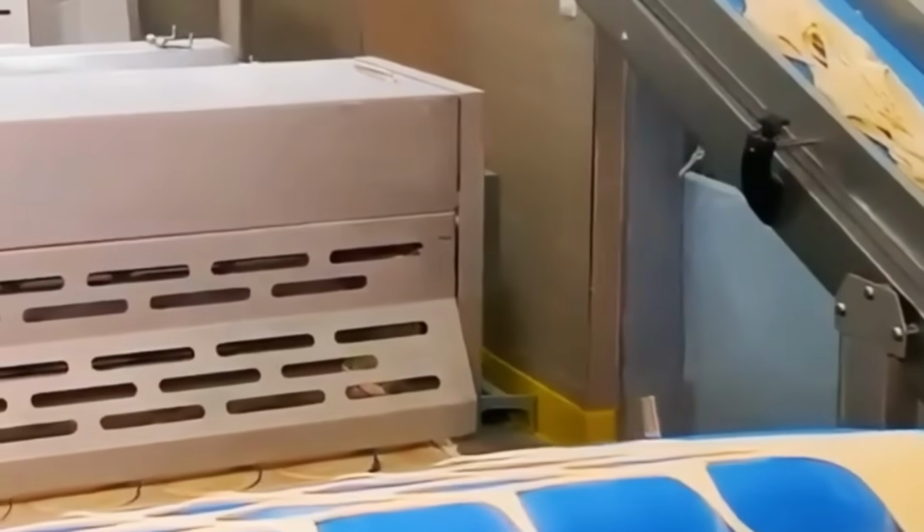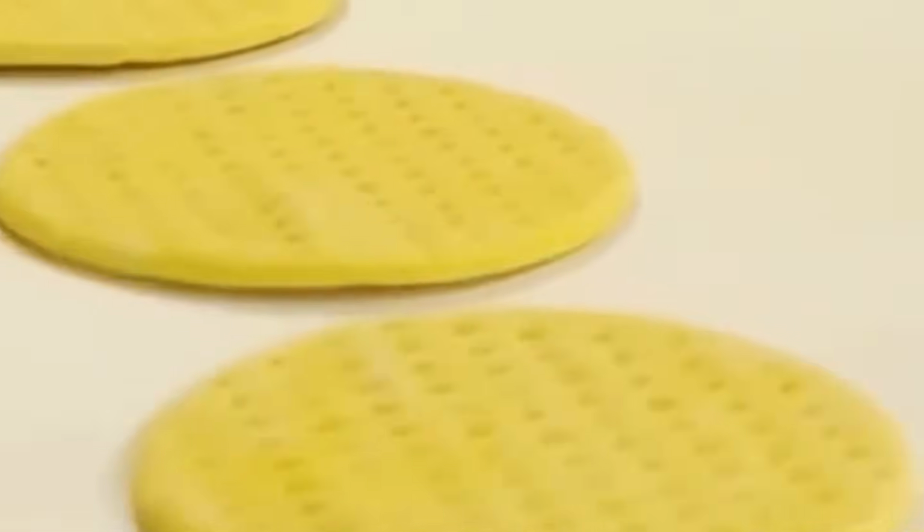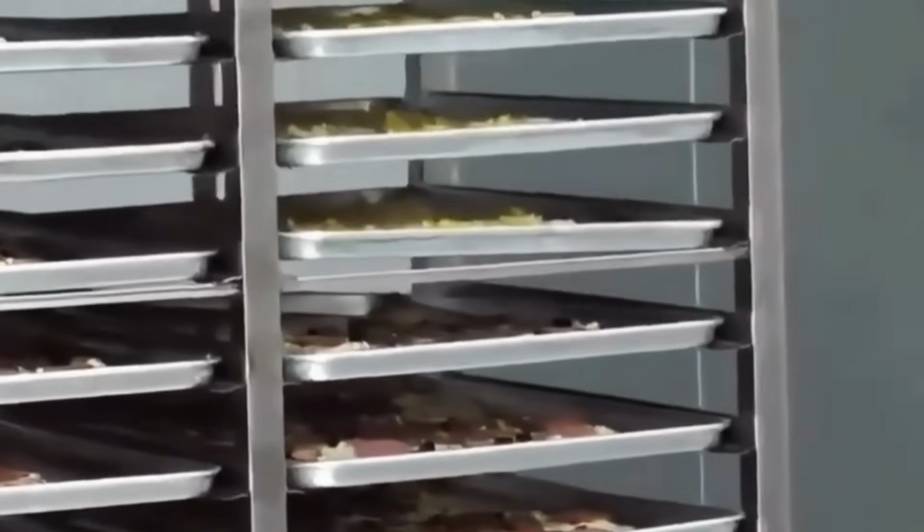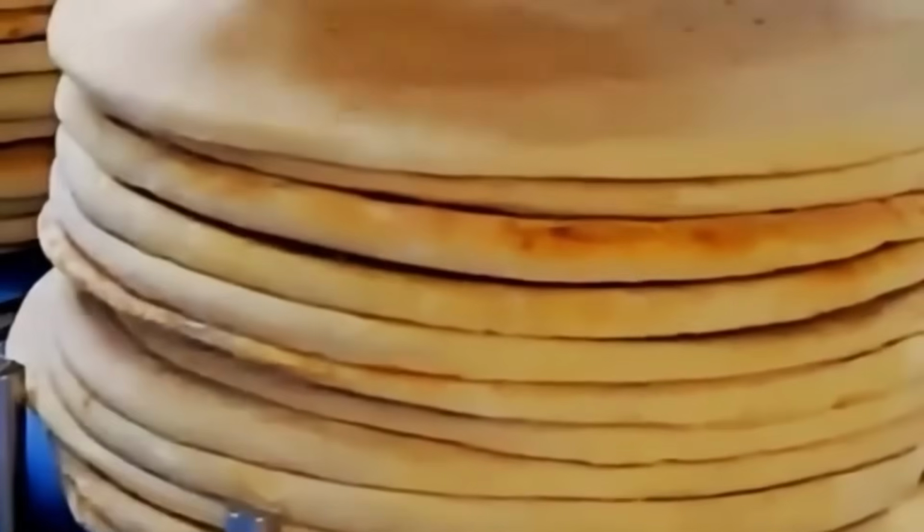The spiral mixer begins in a slow speed mode for 1 minute to hydrate the dry ingredients. After hydration is complete, the mixer shifts to high speed to develop gluten structure. Mixing continues for 8 to 10 minutes until the dough reaches a defined elasticity and target temperature range.